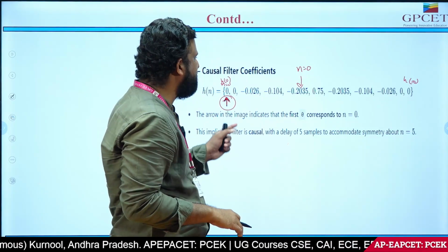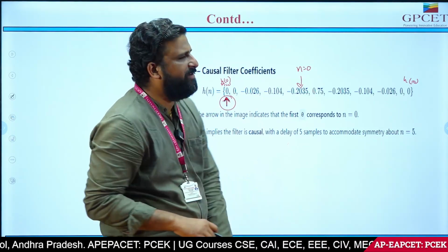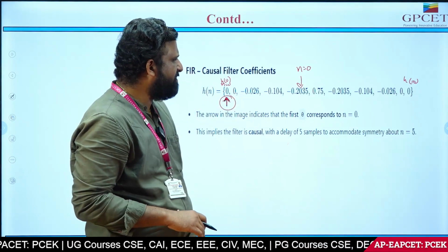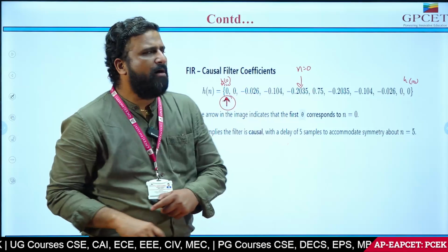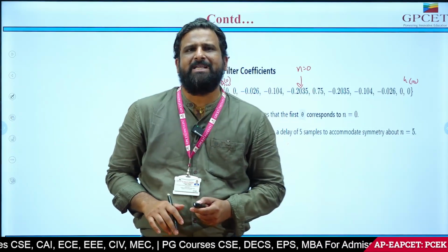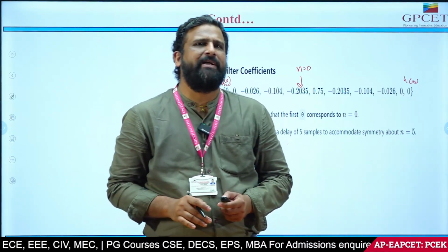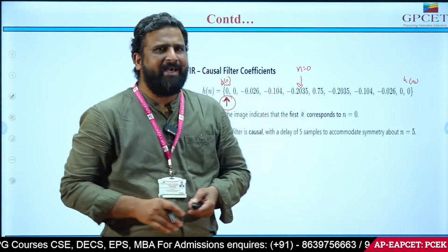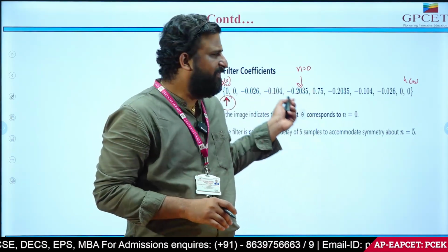With the help of all these causal filter coefficients, we can realize the high pass filter by using the Hanning window sequences. Like this, with all the techniques we discussed in the last lecture, using different types of windowing techniques and their conditions, we can design the FIR filter.